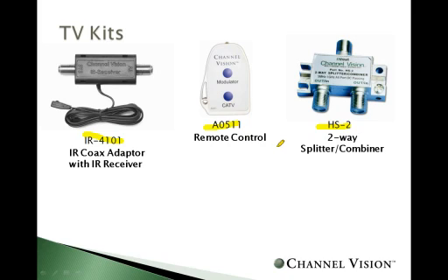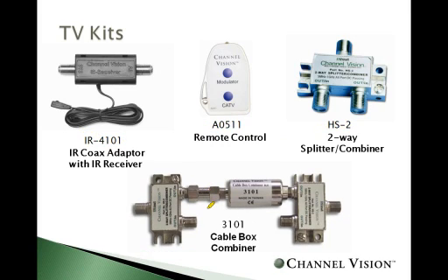Now if you don't have a two-way splitter but you're utilizing Comcast or some manufacturer that does require what's called a DTA box or a digital to analog converter box, you can simply bypass that with the modulator cable combiner just to step around that switch. Now, I will need each one of these devices for every television that wants to see the modulated signal. And don't worry, not a lot of money in this system here. Not going to cost you a lot of money. This little remote control can be programmed into any learning remote control. Simple two-button design. You can also program it into a universal remote control and use a macro and tell it to change inputs on the television at the same time. Or, well, keep it as a handy little device to manually select it with that.